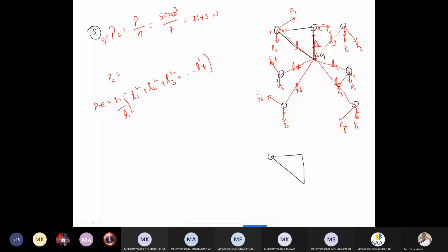This is the first rivet. This is the 100 mm given in the question. This is the L1 that we need to calculate. Now this is the CG for the system, and this is the second rivet. Now how much is the distance from here to here? Suppose from here to here it is 200, it means it is 100, it is 100, total 200.